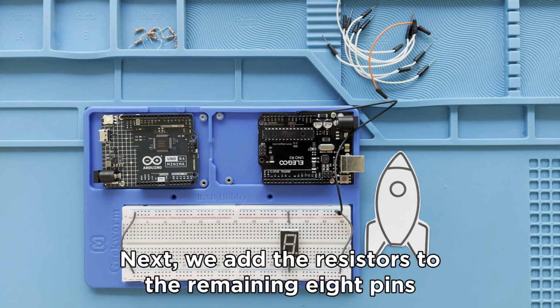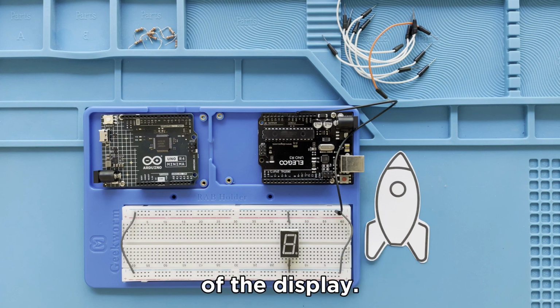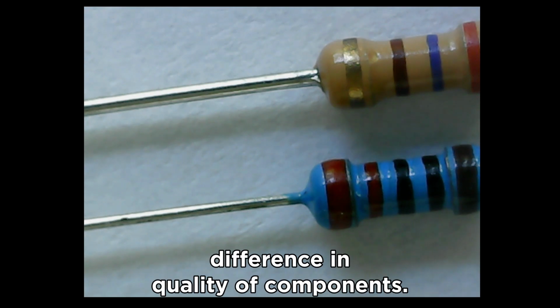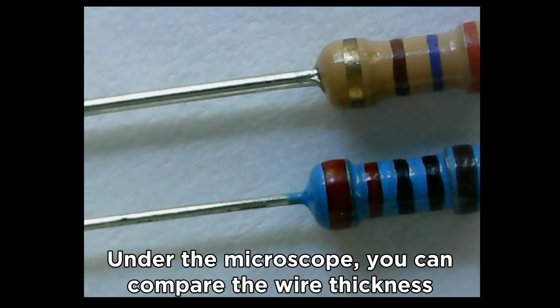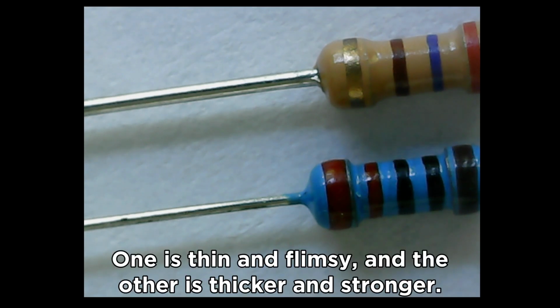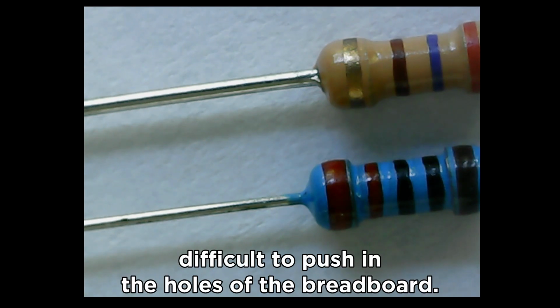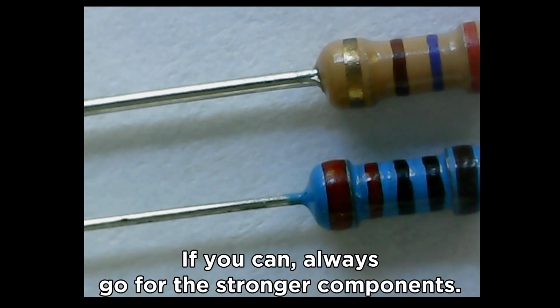Next, we add the resistors to the remaining 8 pins of the display. Here I would like to pause for a moment and show you the difference in quality of components. Under the microscope, you can compare the wire thickness of the resistors. One is thin and flimsy, and the other is thicker and stronger. The thin wires will break easily and will be difficult to push in the holes of the breadboard. If you can, always go for the stronger components.